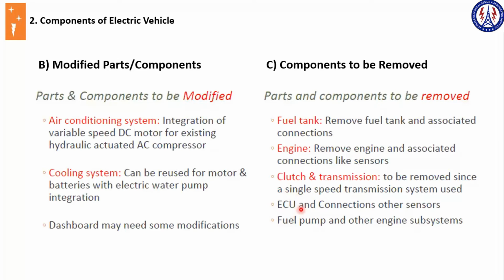Some sort of PCB and relay is there, showing to the user. So that will also be replaced or removed, because the existing one won't be feasible to manage your battery BMS and all. It was designed for a specific purpose, but now it's an entirely different case. Then the fuel pump and other engine subsystems also need to be removed.